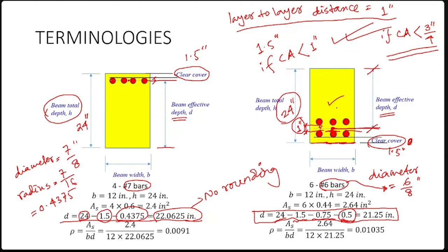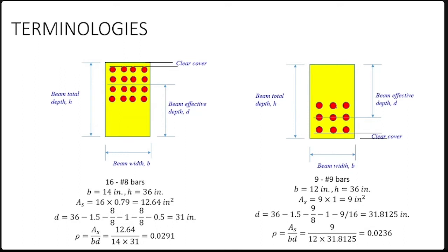Okay, I have a few examples. In the next example, we will calculate the effective depth. At first, you need to locate the centroid. There are 4 layers, so the centroid must be right at the middle. Do you find the red dot that I wrote just now? Yes, sir. So from this dot, you will calculate the distance to the opposite surface of the beam.